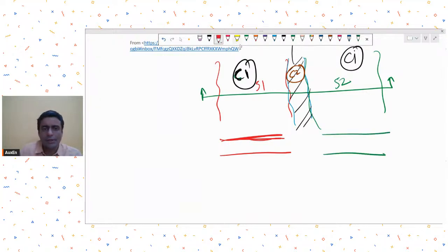By vertical joint, I think he means a joint like this in the pour strip, vertical. If I properly understood, my answer is that, not only in pour strips but otherwise also, we try to avoid having a vertical joint in slabs. Usually we have it at a slant.